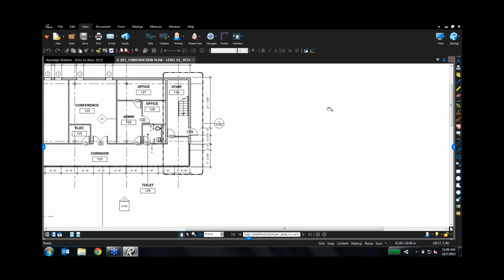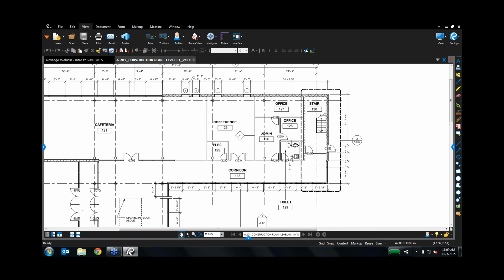Okay. As a quick aside, while we're speaking of tools for doing comparisons, Bluebeam Revu does have several comparison tools built in. For document comparison, I've got compare documents and overlay pages. Now overlay pages works just like a light table. You pick a couple of plans, for example, your mechanical, electrical, and plumbing plans, and they each get a different color. They're laid right over each other as layers, and you can do coordination that way.